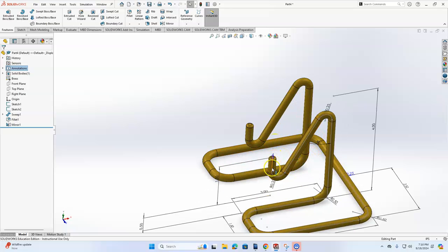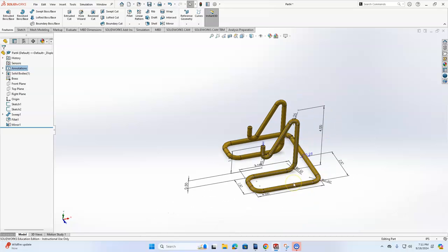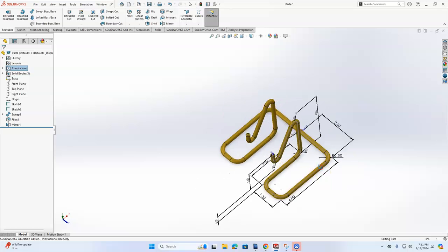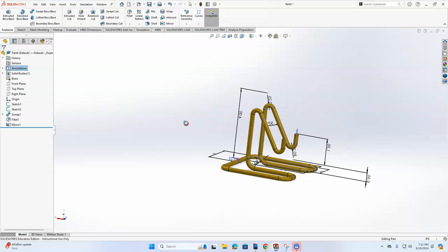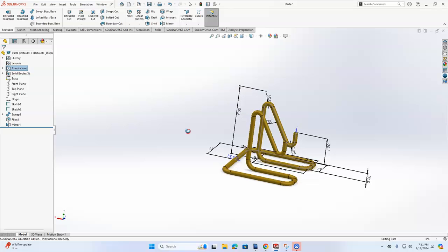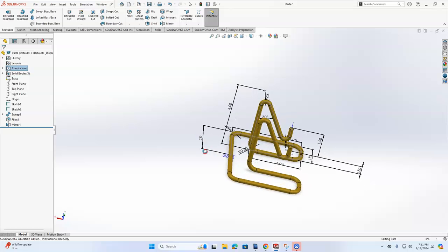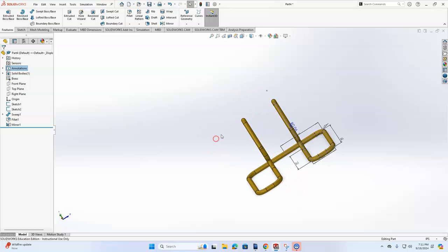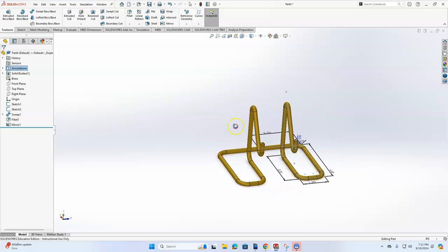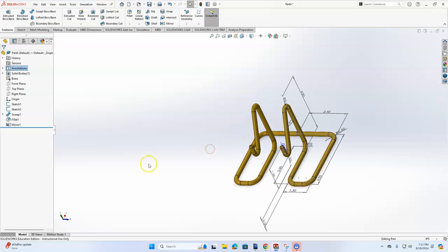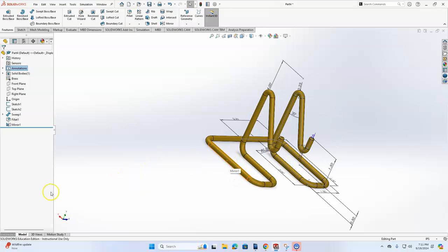Well, we would need to make a bunch of different extrusions, revolution, extrusion, revolution, extrusion, and so on. So it would be a nightmare of a project. And here we have demonstrated that essentially in 10 minutes you can create this project, if you identified the feature as the right feature, and in our case, this feature was the circular sweep. Thank you for watching, and now let's work on the project.